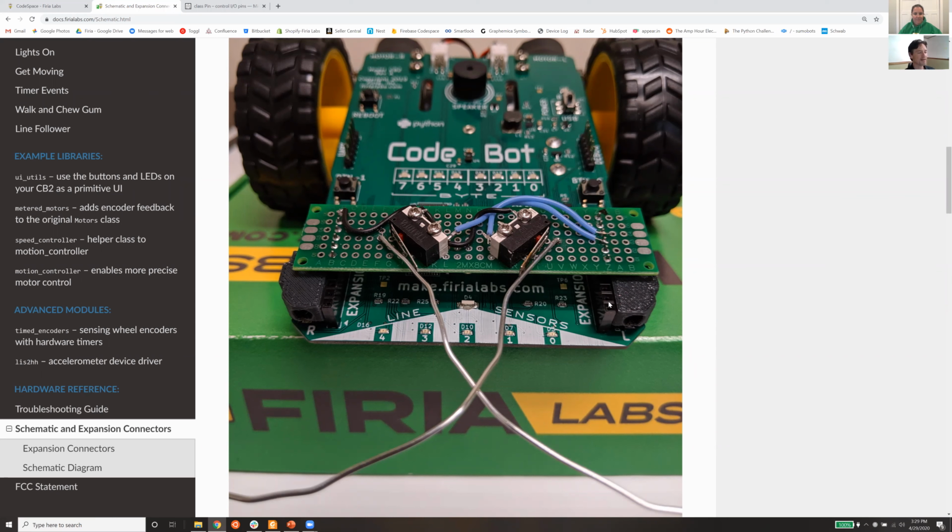So you can see the pinouts on the schematic that show you, like, pin 1 is marked with this little triangle here. And then we're just connecting into power and a couple of IO lines, or actually I think it was just ground and a couple of IO lines. And we let these micro switches tie 1 or 2 different GPIO pins. We could enable internal pull-ups, and then they're just gonna be tied to ground based on which one is, or both, activated.